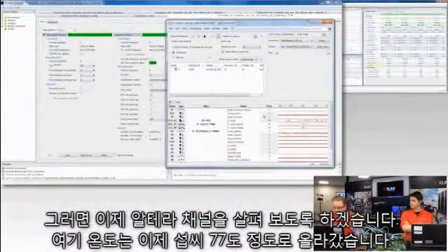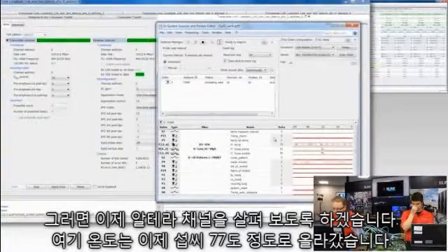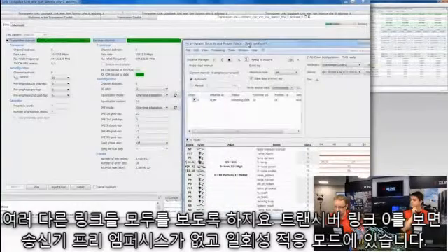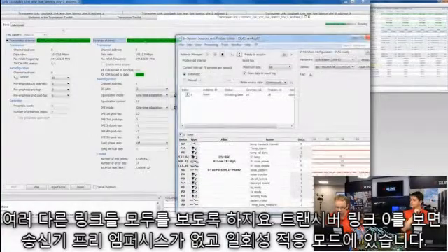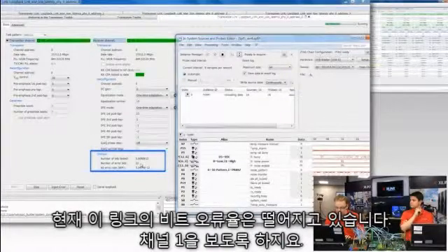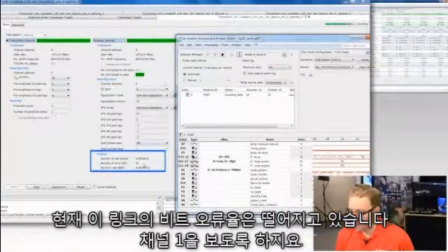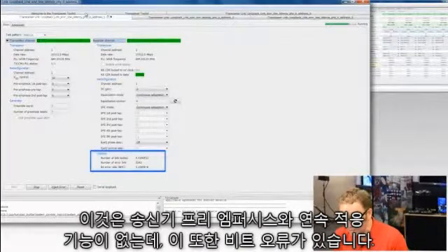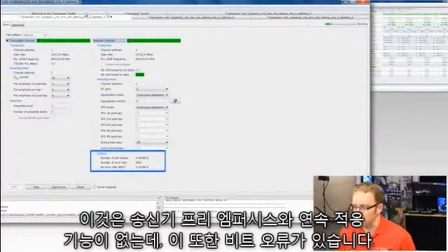So now let's have a look at the Altera channels. The temperatures come up here now to about 77 degrees Celsius. And if we go and have a look at all of the different links, we look at transceiver link 0 with no transmitter preemphasis and one-time adaptation. We're currently dropping bit errors on that link. We have a look at channel 1, which has no transmitter preemphasis and continuous adaptation. It also has bit errors.